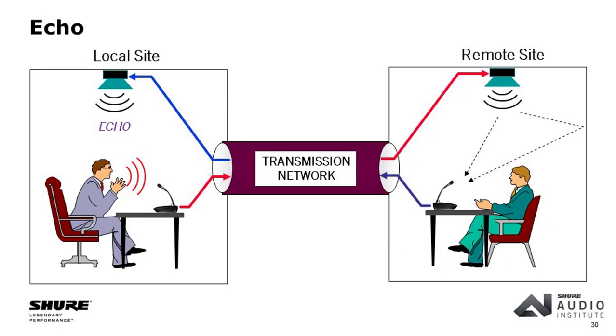And there's really only one good solution to this, which is that we need to use an acoustic echo canceller, which prevents the sound coming out of the loudspeaker from being retransmitted through the microphone. It gets removed electronically. The tricky thing that a lot of people forget is that an echo canceller is something you use to prevent sending echo to other people that they will hear. So if you're hearing echo, it means the other guy needs an echo canceller. There's really nothing you can do to prevent them from sending echo back to you.